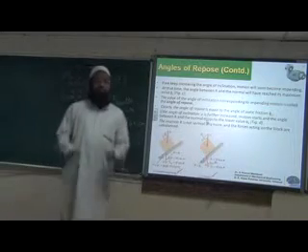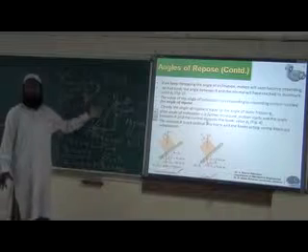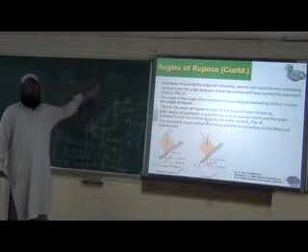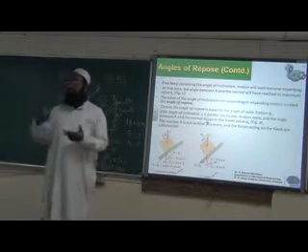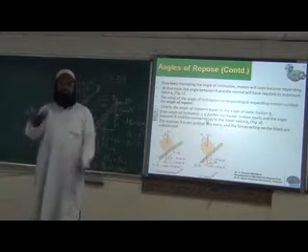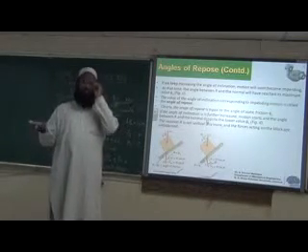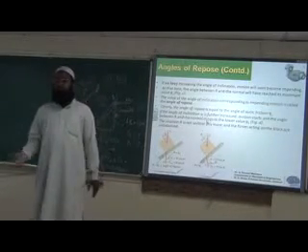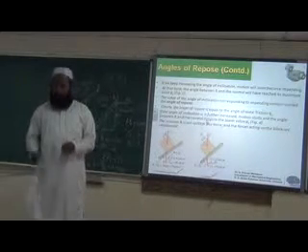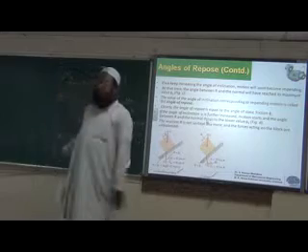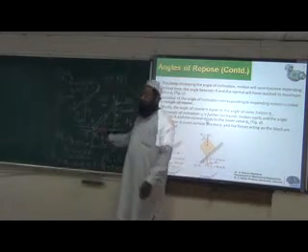This is a simple ladder problem where only the self weight is considered. You may have a problem with a man standing on it, some load standing on it. If you know the position, you will have more forces acting on this ladder, so we have to resolve with sigma fx, sigma fy, and do it. Any doubt in this?